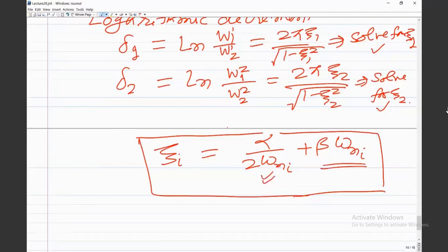So more or less the damping would be accounted for correctly for different modes, even if the higher modes are excited due to dynamic force. Even though we are just using two modes to find alpha and beta, the increasing damping with frequency or mode number is actually captured by this Rayleigh proportional damping model. So it would still be accurately represented for other modes.